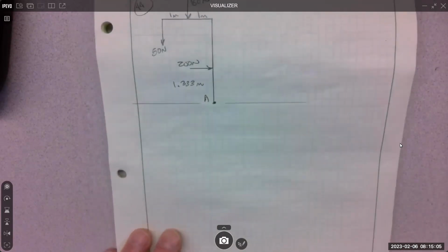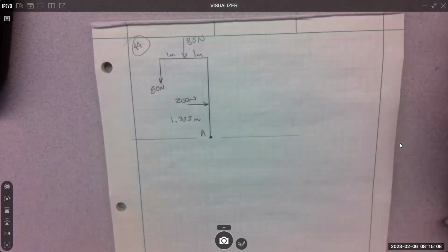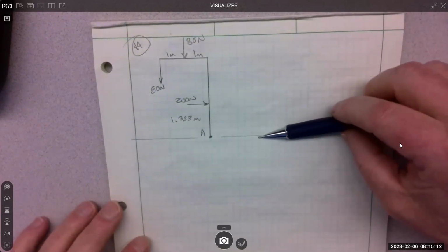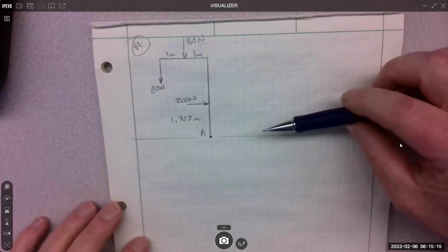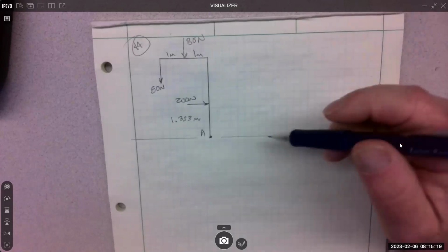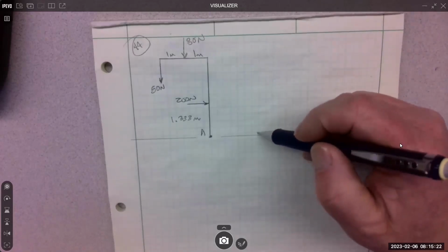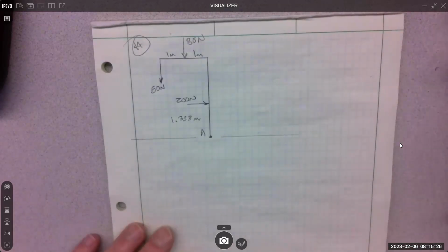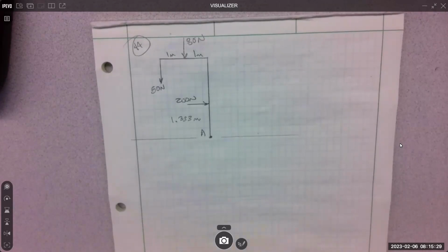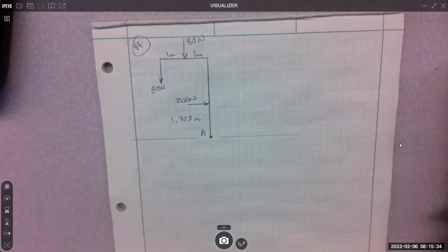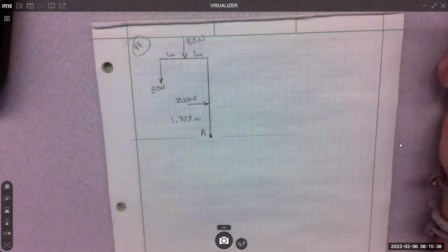44 looked like this. And I think, again, didn't have my book, but they must ask for where the resultant intersects the ground or something. Is that what they wanted to know? Find the resultant and where it intersects the ground. Is that true? Yeah. So find the resultant means move everything to one spot. This is a non-concurrent. All these forces do not intersect each other at one spot. So that means we have to collect everything at A.